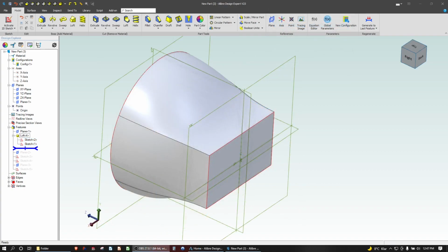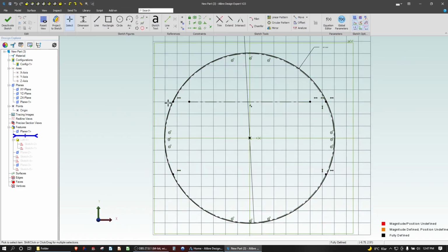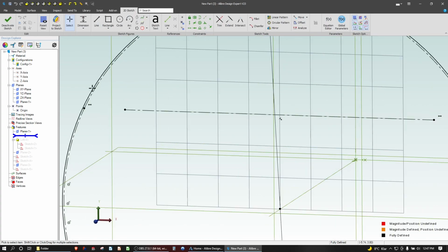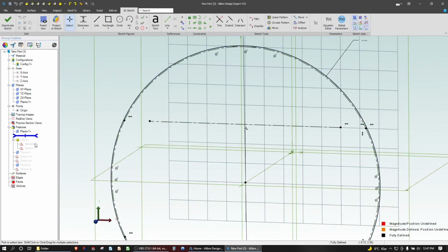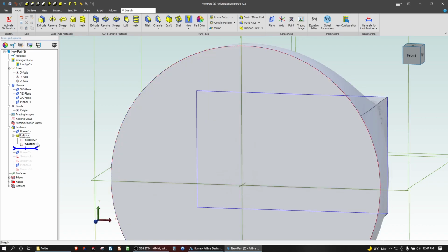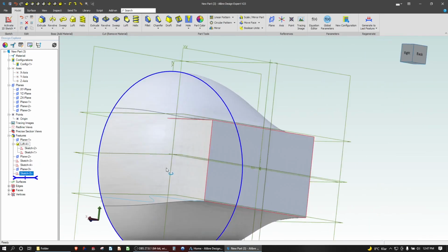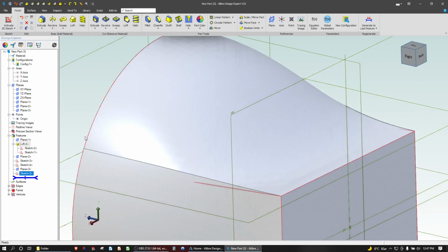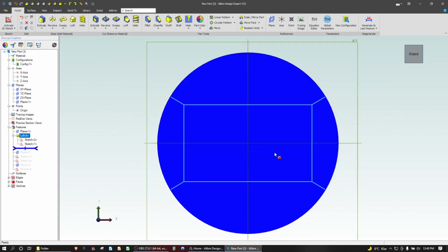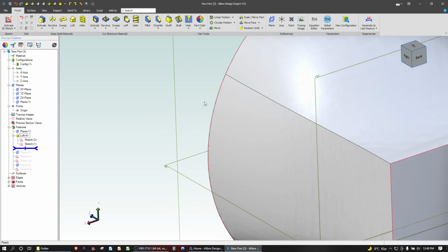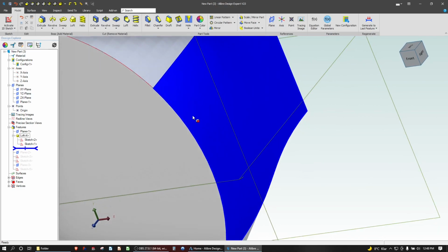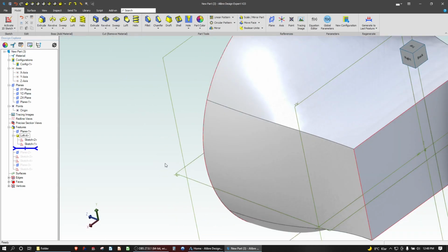So, and one more thing I forgot to mention, let's just do a quick little experiment, because right now on sketch 2, our sketch profile is a circle, right? So our 4-pointed profile is imaginary or construction, and our circle is just a circle. It has no vertexes on it. So let's deactivate the sketch. A little experiment here. We're going to generate all of our other guide curve sketches, and our circle, I do need to fix this one thing. Actually, before I fix it, let's do another experiment, right? So our circle is slightly bigger than where our guide curves are meeting up. So our guide curve sketches don't actually intersect the circle.